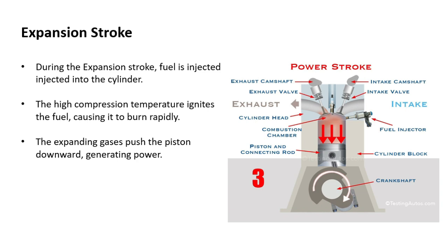into mechanical energy. So the fuel itself contained a chemical energy, and we combusted the fuel. We took that chemical energy and we transferred it into the heat and pressure, and then we use this heat and pressure to drive the piston downwards, and in doing so we are converting the energy into mechanical motion. Now, if you could isolate the power stroke without needing the other three strokes, then we would have a very efficient engine. But unfortunately, we cannot do that.